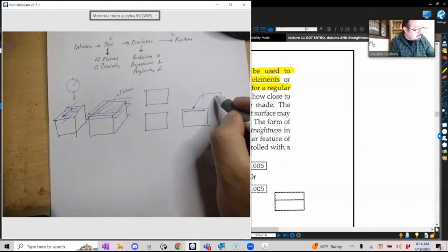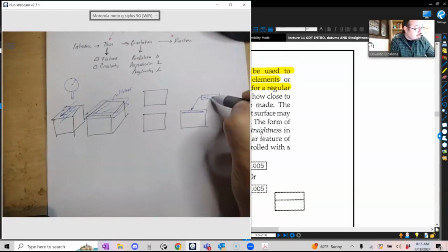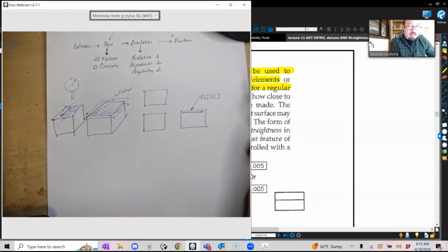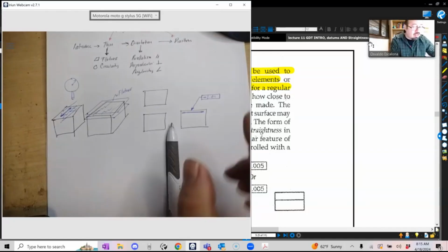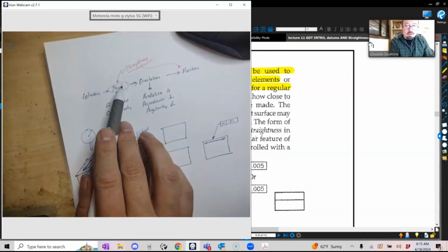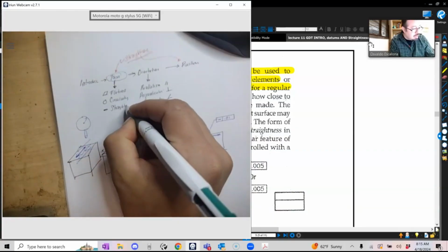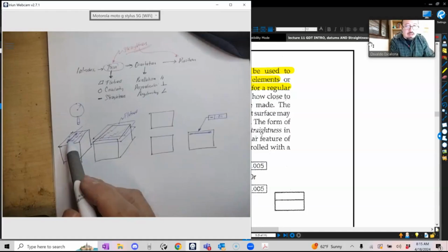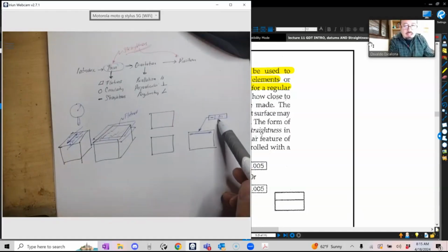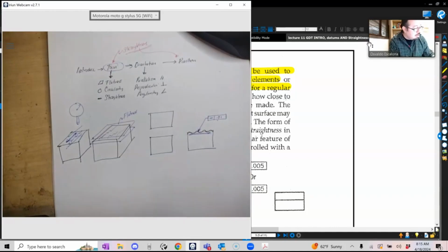So you put a feature control frame, and then you ask, okay, how do I put the straightness? Straightness just looks like a line, just straight. And then you give it a distance, I don't know, 0.01. Keep in mind that I'm just looking at straightness in a single direction. I have no datums or nothing because it's a form. I'm just controlling the form. So straightness of a surface is two parallel lines separated apart by the indicated distance of the tolerance zone. My part gets to deviate along these two parallel lines, and they are independent of each other.